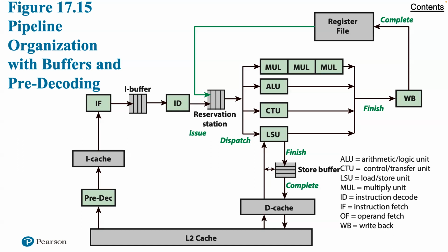This feature is especially useful for loops in which data created in one iteration is used immediately in the next iteration. On loads, the LSU examines the store buffer as a look-aside buffer and extracts the data from there if available. Otherwise, it queries the data cache as normal.